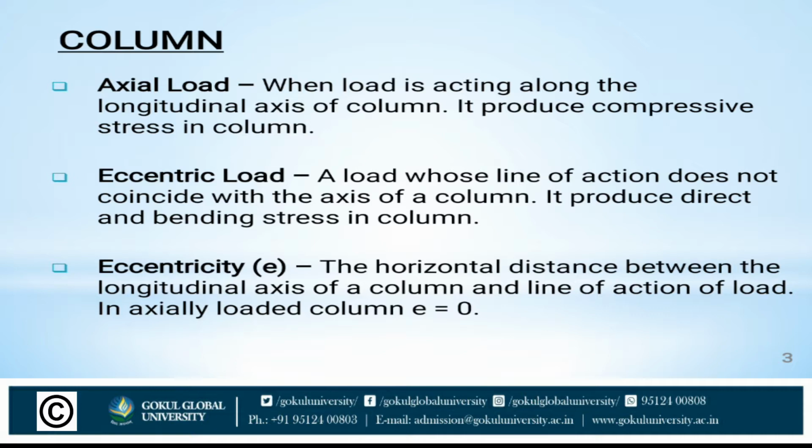It's called eccentric load. Eccentricity e: the horizontal distance between the longitudinal axis of a column and the line of action of the load. In an axially loaded column, e is equal to 0.